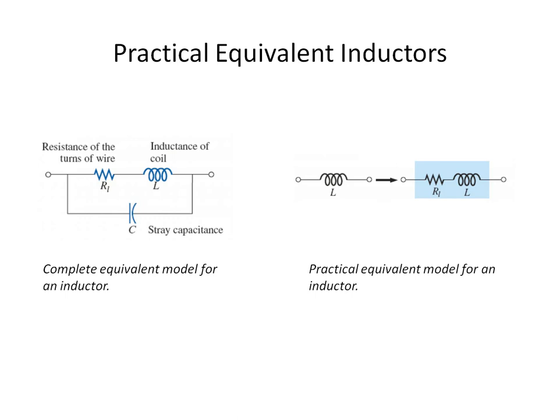Now, when we're talking about inductance and the ideal inductor, pretty much all we think about is just the inductance part. But unfortunately, inductors are not ideal, and so they have other factors involved. One of them is the resistance of the wire itself. The other one is because of the turns in the coil. One turn to the next is going to introduce capacitance. So that's going to be another aspect.